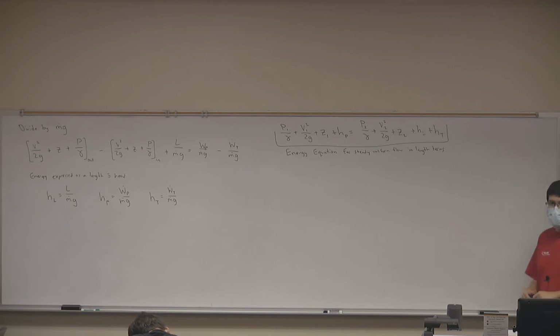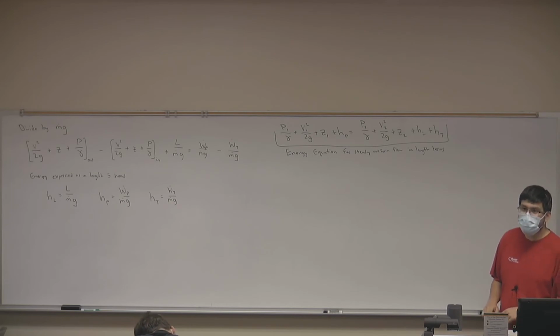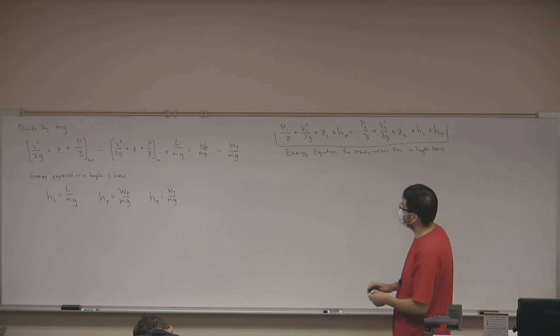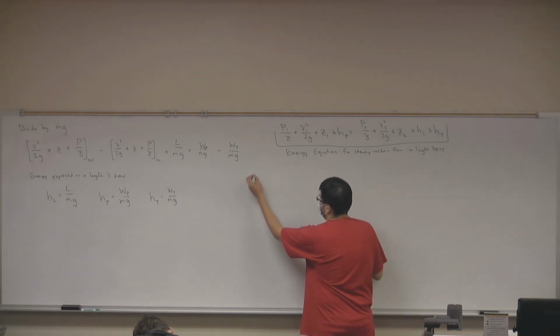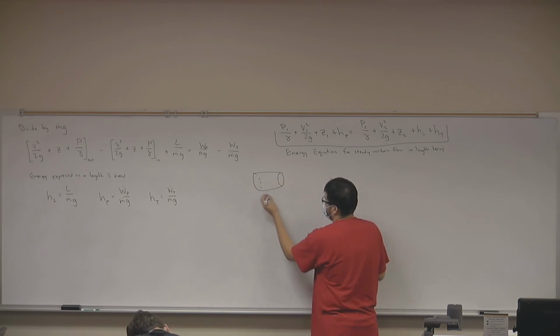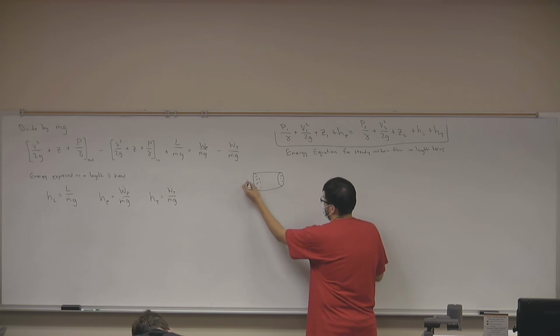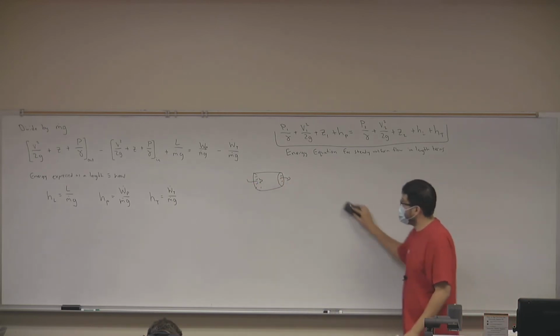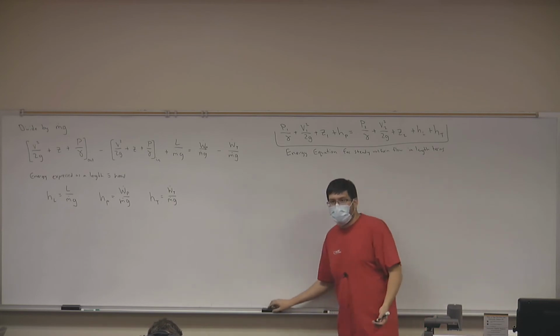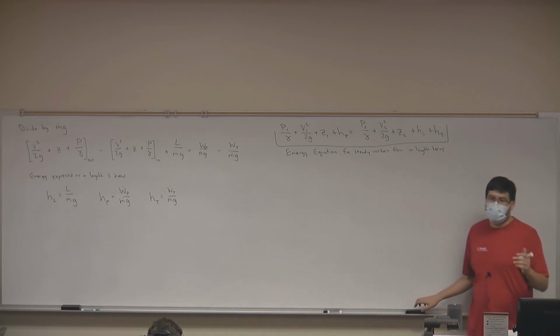I have a quick question. Sure, throw it at me. Well, never mind. It just went away. Well, I was gonna ask you for the area right here with the dA. It's the cross-sectional area, right? That's correct. So when we're looking at any control volume, that area should be equal to just the area of the control surface, the area where things enter and or leave your control volume. That's a great question. When we're looking at a system in a pipe, what do you think the area should be? The cross-sectional area of the pipe.